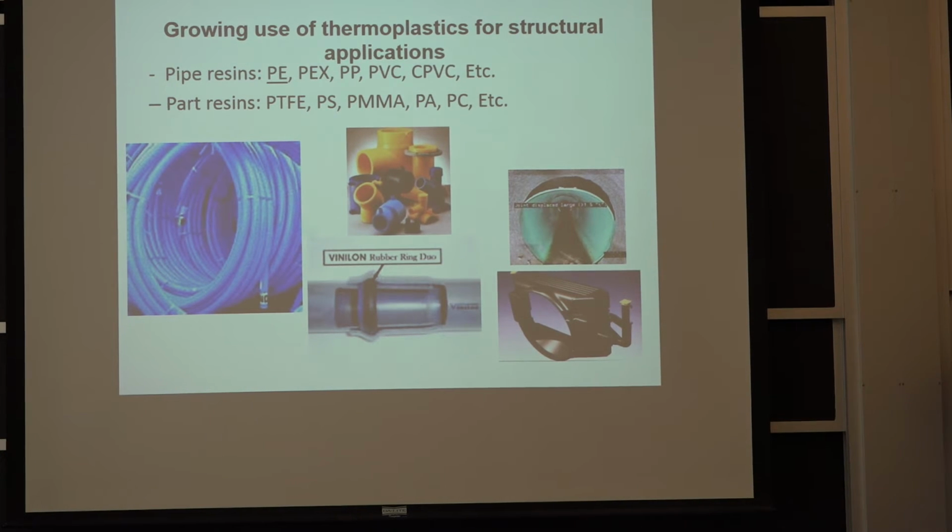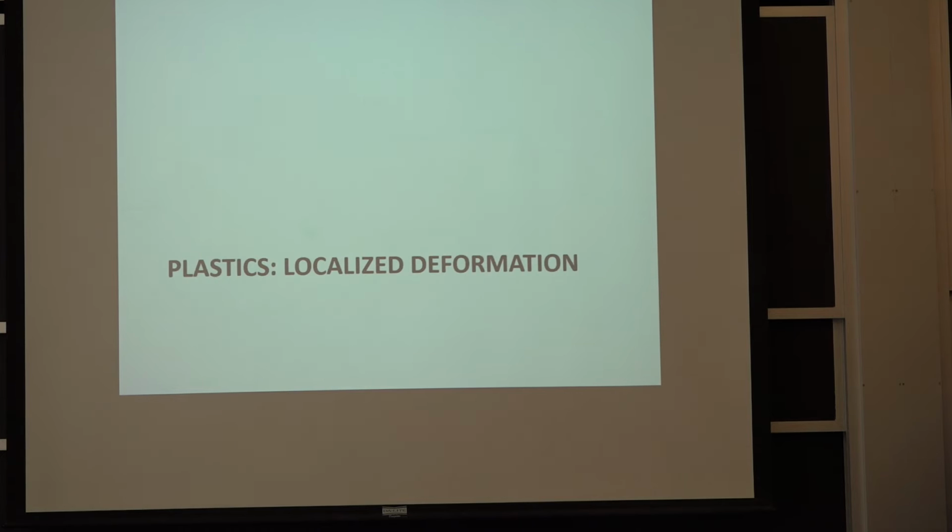So a lot of under-the-hood components are injection molded plastic parts, nylon traditionally, but they've made a lot of improvement. For nylon, the properties are very sensitive to moisture, which is not a good thing. So there have been resins developed that will have a more consistent behavior, whether you are in a dry environment or a very wet environment. So that's been a significant improvement there.